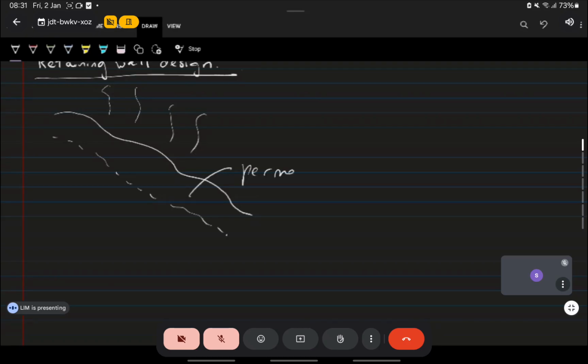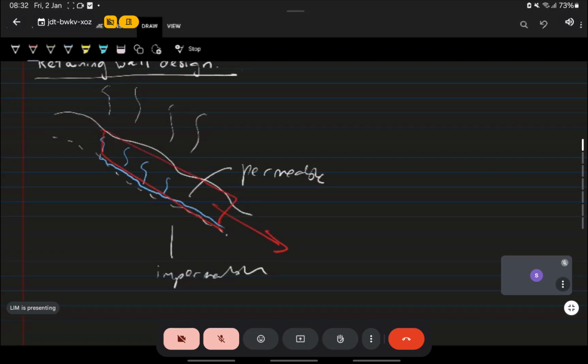This one permeable, the one under impermeable. I'm pretty sure you've learned this in your geotech. Water enters the permeable part, but it cannot enter the impermeable part. So it will flow down the face of the impermeable part. When water flows down that face, it creates a slip plane, and eventually that whole chunk will slide. This is a translational landslide, if not mistaken.